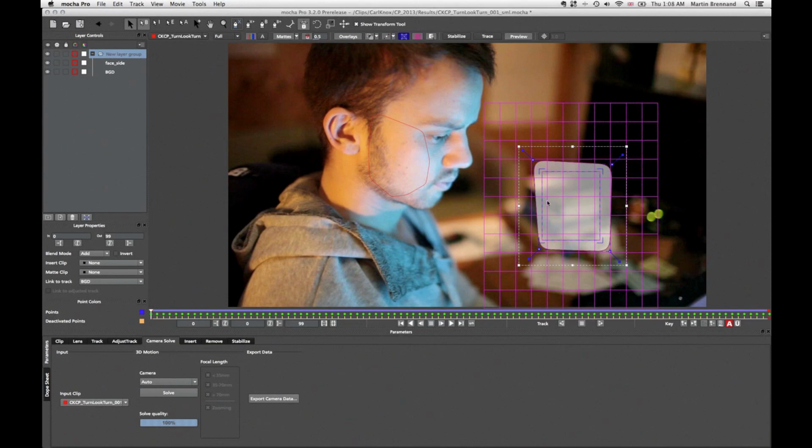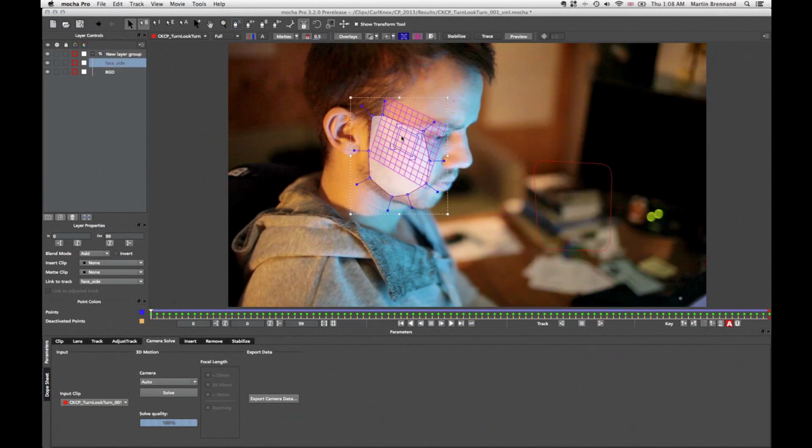The reason we usually get 100% is because nothing is happening whatsoever, because we've given it that dummy data, but it's still given us a camera solve to work with the rest of the information. So once we've done the camera solve, we then select the object that's moving. And here you can see I've localized this surface to an area I want to put in my 3D model.